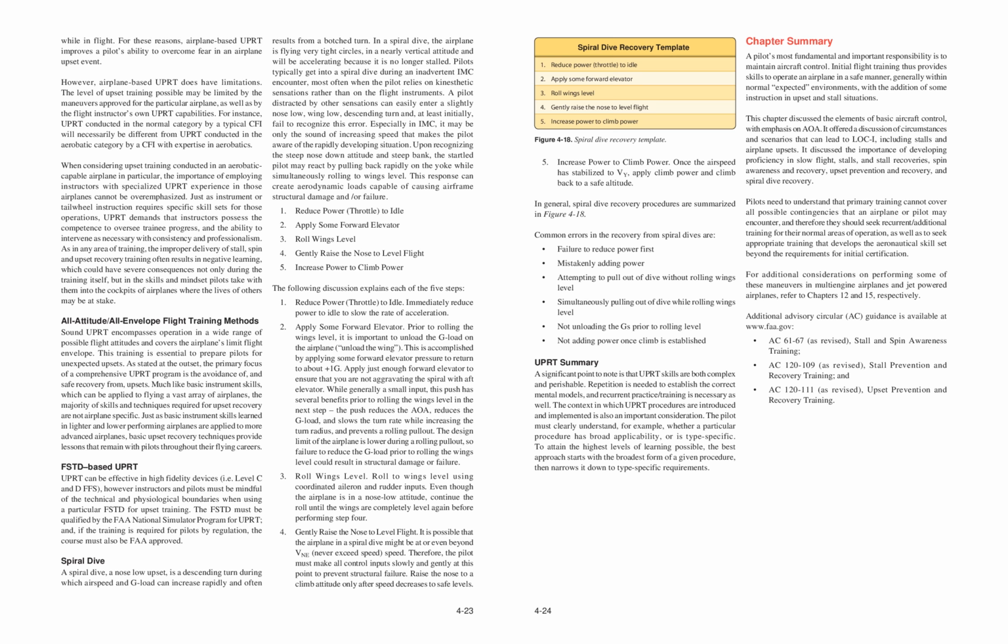4-23. Spiral dive recovery template. 1. Reduce power, throttle, to idle. 2. Apply some forward elevator. 3. Roll wings level. 4. Gently raise the nose to level flight. 5. Increase power to climb power. Figure 4-18. Spiral dive recovery template.